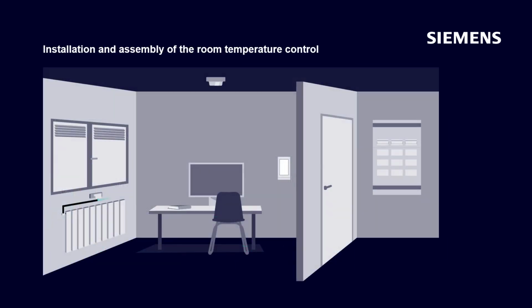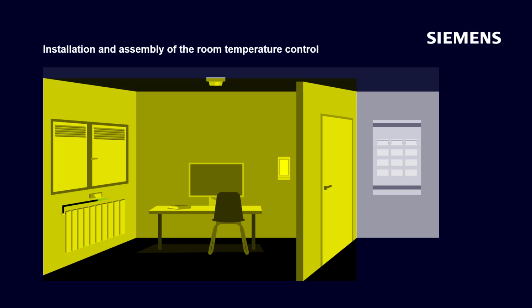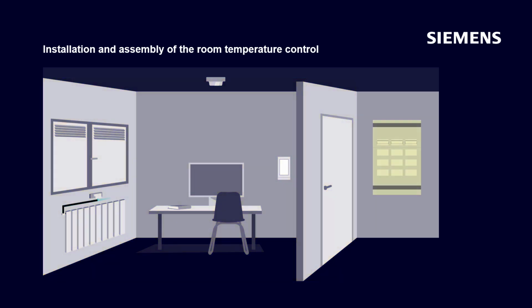This illustration shows a typical room installation for controlling the thermal actuators in a radiator heating system. This is the basis for the following project commissioning. In this example, an office room is heated. The KNX DIN rail devices, such as system devices for the KNX power supply, KNX routers, KNX interfaces, line couplers, gateways, etc., and the corresponding actuators, controllers, and input modules for further functionalities are located in an electrical installation distributor, which is installed in a plant room, for example.